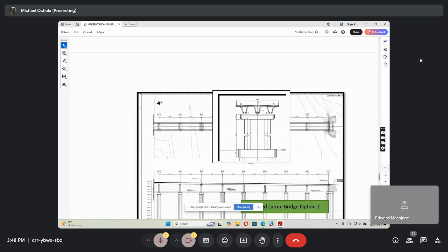Now there's another proposal to have a normal viaduct. This is the type we call, similar to the Isima, but it's called U-type. The bottom one is what they precast, which can be post-tensioned. Then the deck is cast later on in situ. In situ means you place these cast girders up.